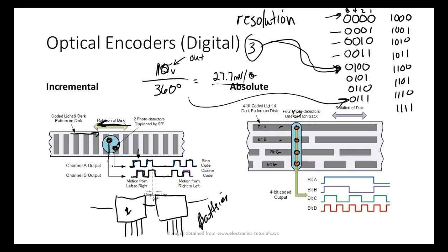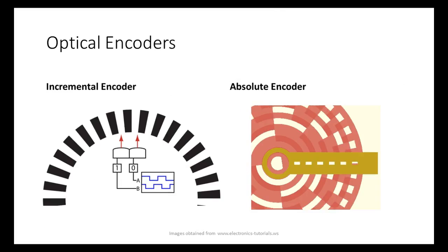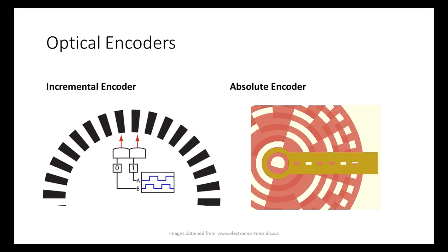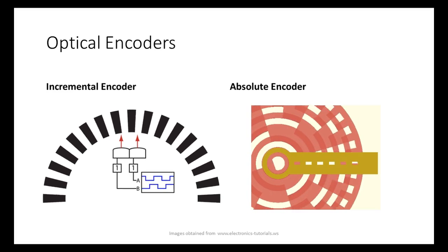Even though we have a quadrature encoder on the manufacturing line, on the Amatrol line, it doesn't need to be a quadrature encoder, because that belt only runs what? In one direction, the conveyor belt. So this is an absolute encoder on the right. This is a quadrature encoder.